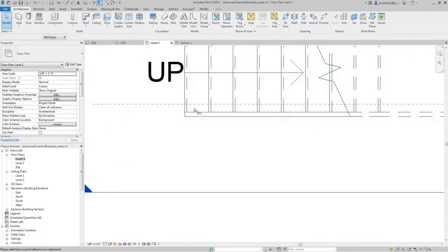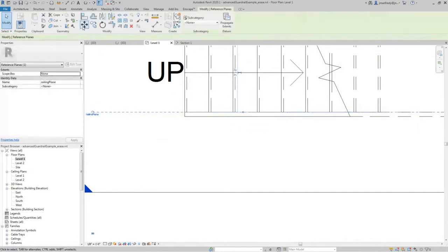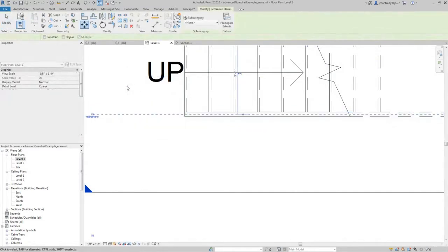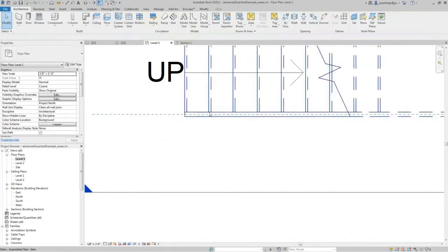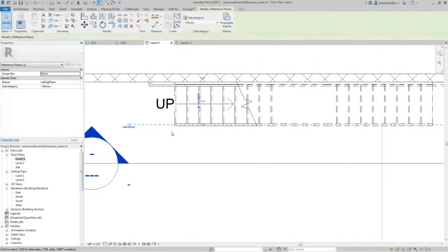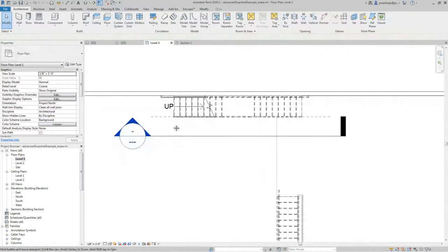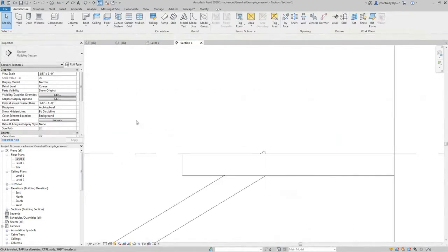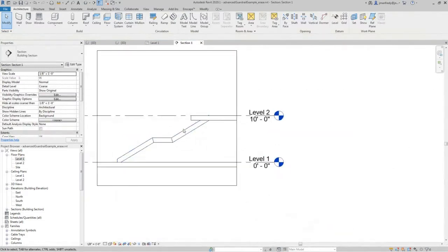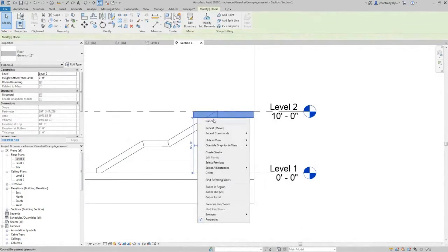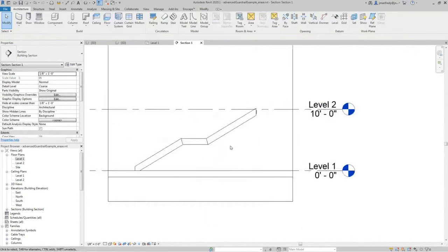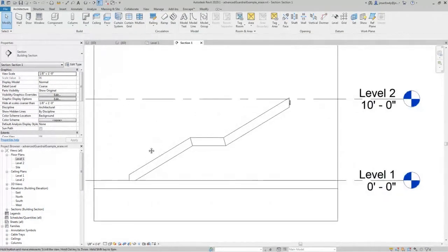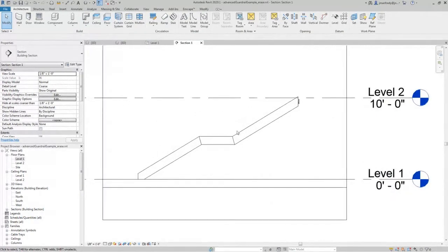Let's say I want the railing to be aligned with here, and then I'm going to move it down a little bit. I'm going to move it down an inch. So I want the railing to be centered right there where that green line is, my reference plane called railing plane. Then what I do is I switch gears and I go to elevation view, and let me hide this floor for a second, hide element. I'm going to tell it to draw my railing in elevation. So I'm going to sketch it out here.